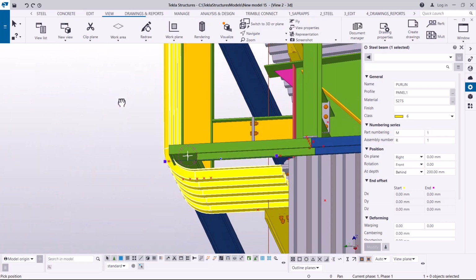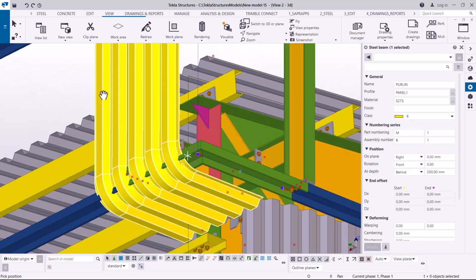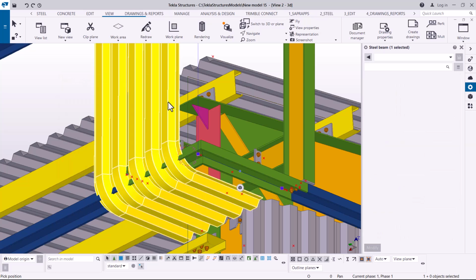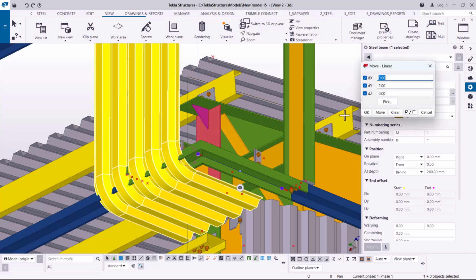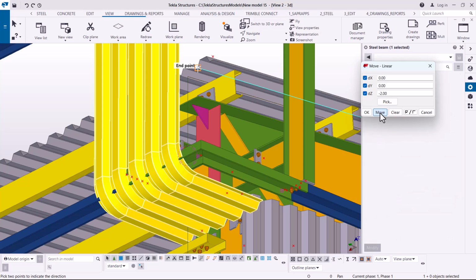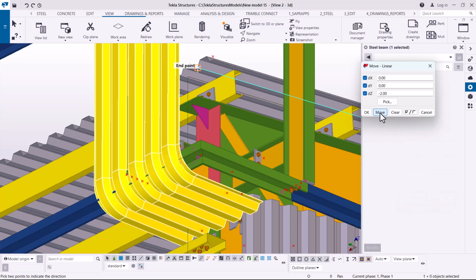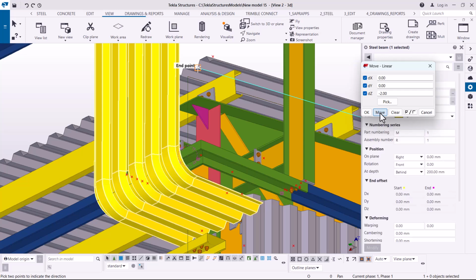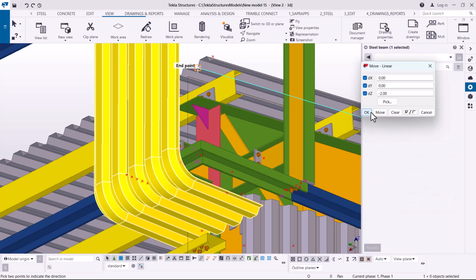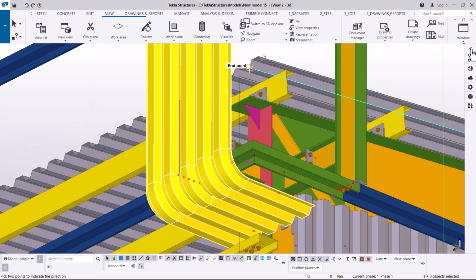So here we are also going to use a move command. I'm going to pick it, select it, then come to special move and come to z-axis here. Under z-axis, I'm going to prefix that with a minus because we're moving down against the direction of the y-axis, and we are going to move slightly in steps of 2, until we come off the clash with the purlin there, or the framing member of the fascia framing. Let me just click on that.